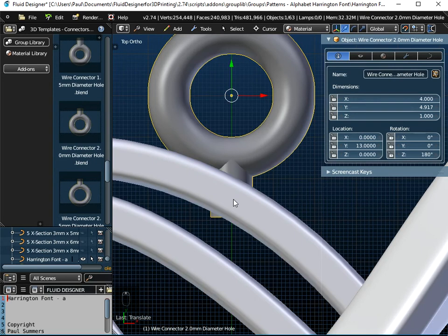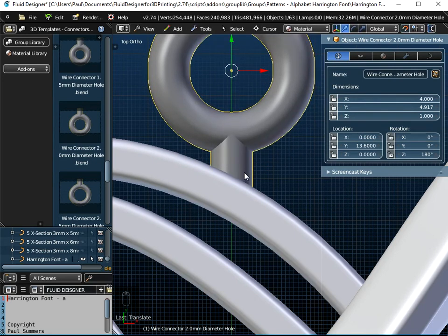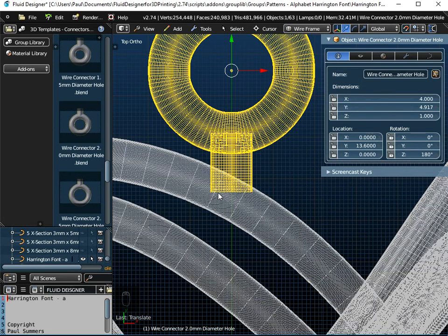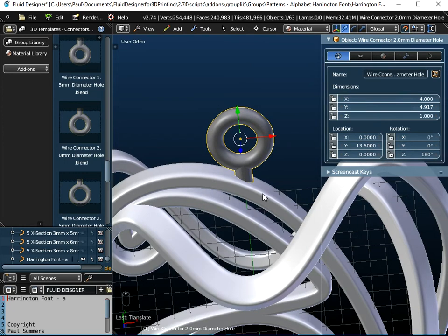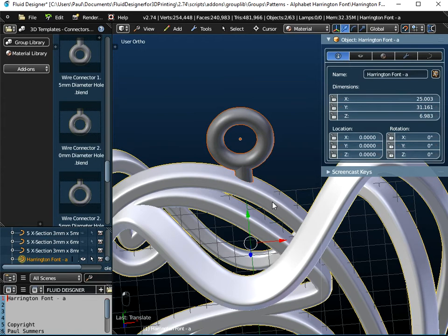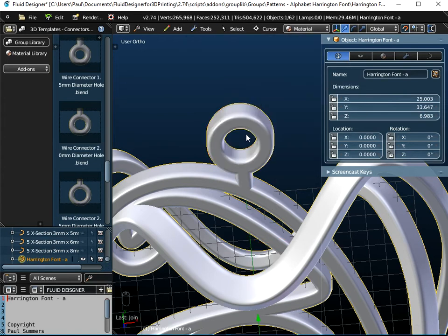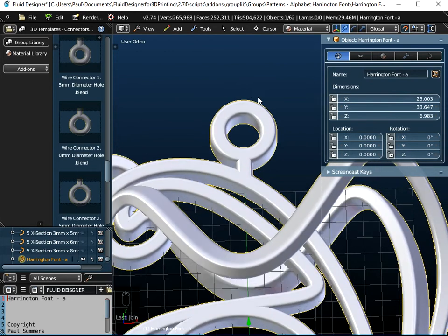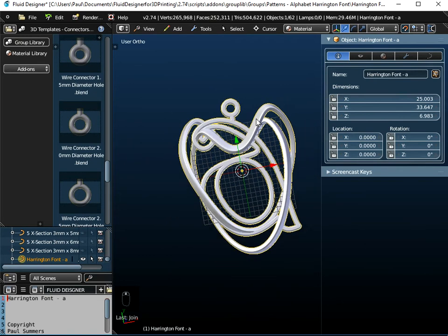and I just need to position it, and zoom in until I get down to millimeters. You need to position it so that it is just fitting in there, and you can check that by going into wireframe. So you can see the bottom of this is inside my pendant now. And again, if I highlight that object, hold down the shift key and highlight my pendant and join them together, it will take on the thickness of the actual pendant, and the entire thing will be a parametric